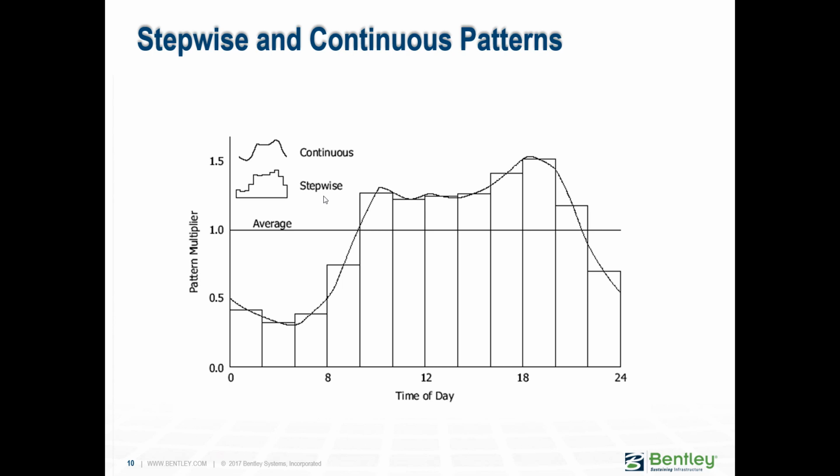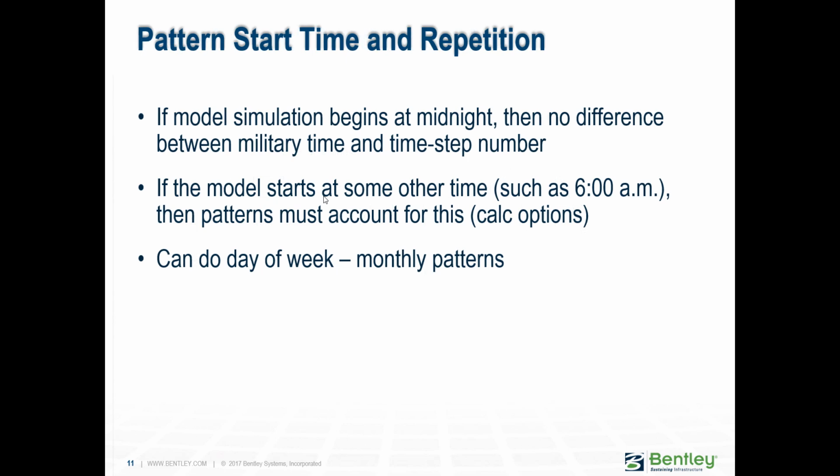So if you have one for those, then great, because that would help you come up with your commercial pattern separately from your residential and your industrial. Sometimes what we end up doing is that if there is a large user, like an industry, and if you have data particular to that user, then you can generate a pattern for that node and kind of separate it from the rest. But again, it all depends on what you have.